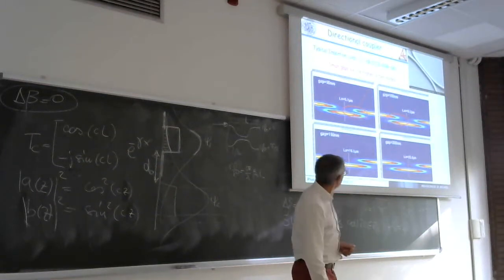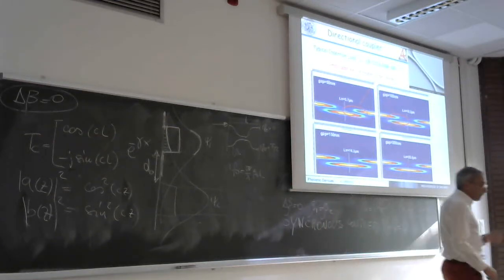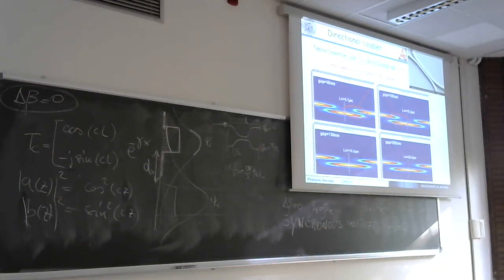This is another simulation of a directional coupler. This is for silicon photonics, so the dimensions are very small, the gap is very small. Here you see the two waveguides. We enter from here, and you see that the mode propagates. After a while, you have light also on the lower waveguide. It continues to propagate. This is the coupling length, or L_C or L pi, and you get the maximum transfer of total power because it's synchronous, and then it goes back.